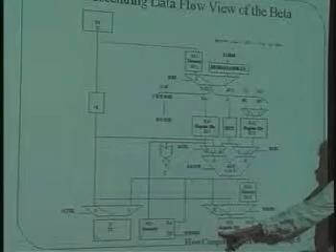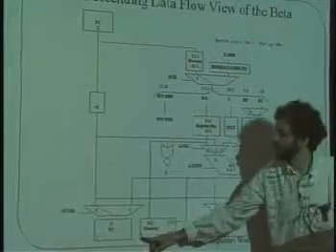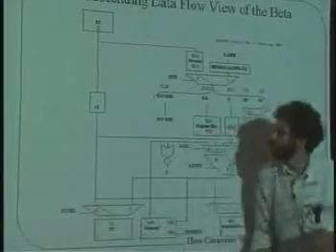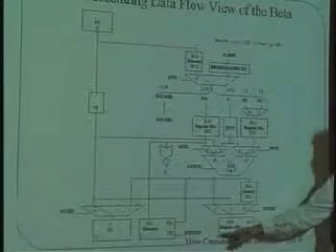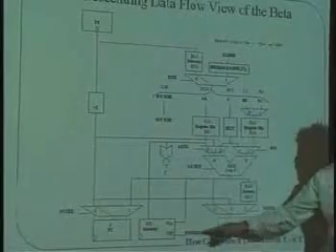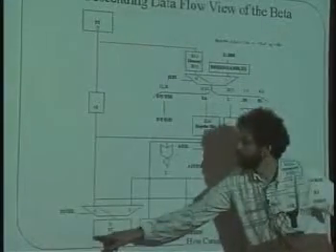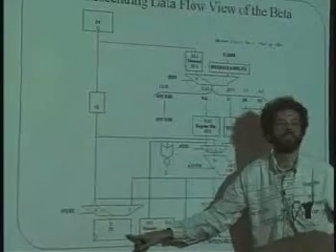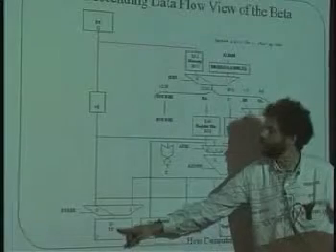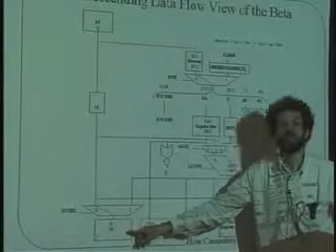A clock is given by the arrow sign that's on the left-hand side here, okay? And so every time we want to process the next instruction, there's going to be an upward going clock on each one of the arrows down here. And the PC will always be incremented, or it will always change. So for the clock that goes into here, notice that there is no E here. So this part of the storage, the register that is the PC, will always be written every clock cycle, every time the clock goes off.